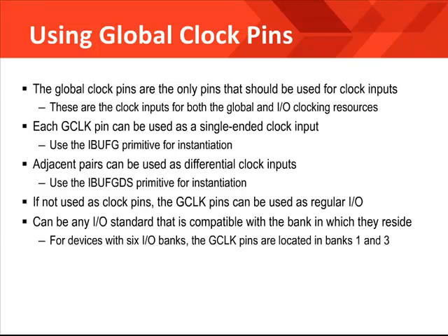The pins can support any I/O standard that is compatible with the I/O standards used in the same bank. This is required as part of the I/O banking rules. These rules require that input pins share the same power supply in a single bank, and that output pins share the same power supply as well.